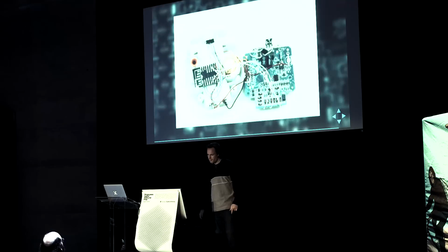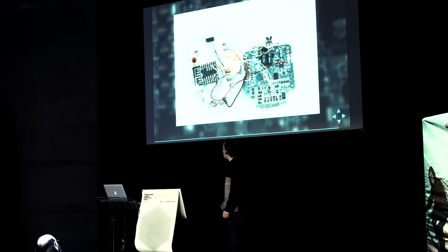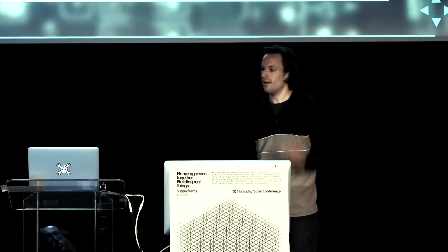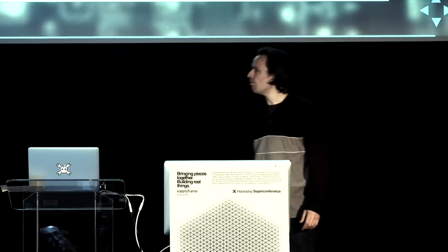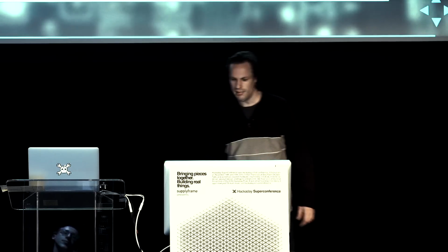The hardware also is pretty simple. It's a mess of wires, but it works. You can basically see an ESP12 module up there, which is connected to the 3.3 volts from the batteries, which actually runs just fine. It has a programming port in place of where the figurine would go, because I cut out the PCB there anyway. And it has 3 wires running to the buttons, and that's it basically. And you can also still see the bit of flash EEPROM on top, near the infrared transmitter and receiver.